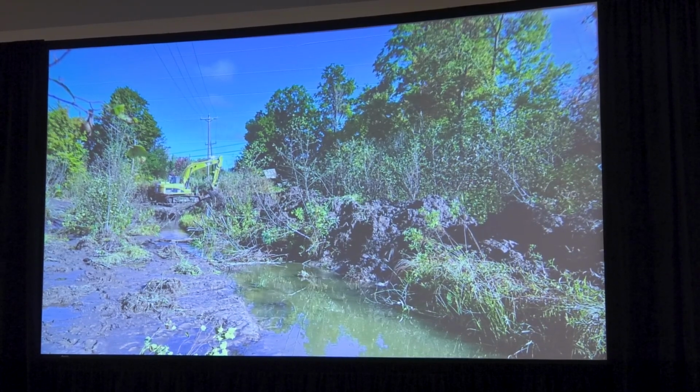So as the contractor was backing out of this soft area on the truck mats, they were replanting native vegetation as they went. So the low, wet-looking side on one side of the channel has been replanted, and then it got flooded, and that replanted vegetation held the soil really well. We really did not have an erosion issue, even though it had just been excavated that very day.